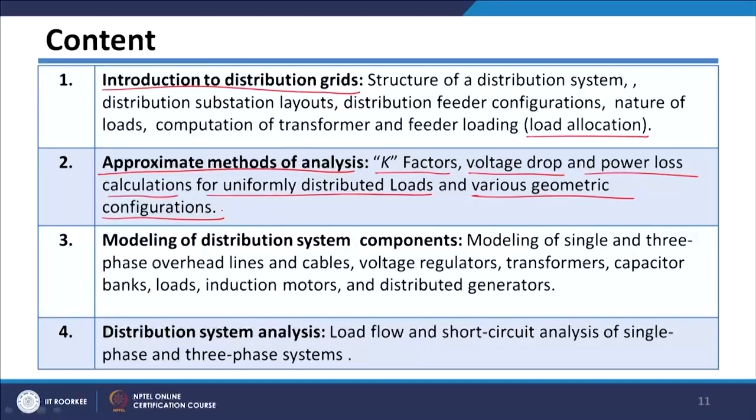Then in the third chapter we will see modeling of distribution system components. In this modeling, we will see modeling of single and three phase overhead lines and cables. Then we will see the modeling of voltage regulator, transformer, capacitor banks, loads, induction motors and distributed generators.